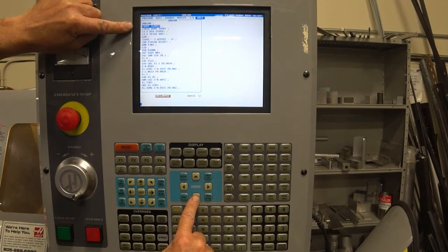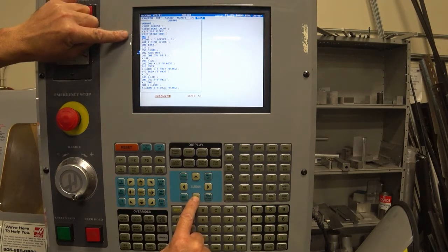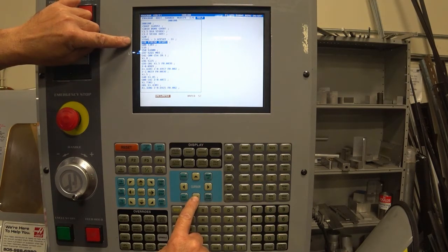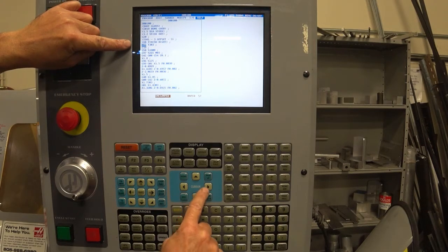After that, you'll see a tool number, T303. It's important to note that this number is actually a 4-digit number, 0303, but the control drops the preceding number. This number is used to index the tool and call out the offset registry values, the pickup, Z and X, as well as the diameter.